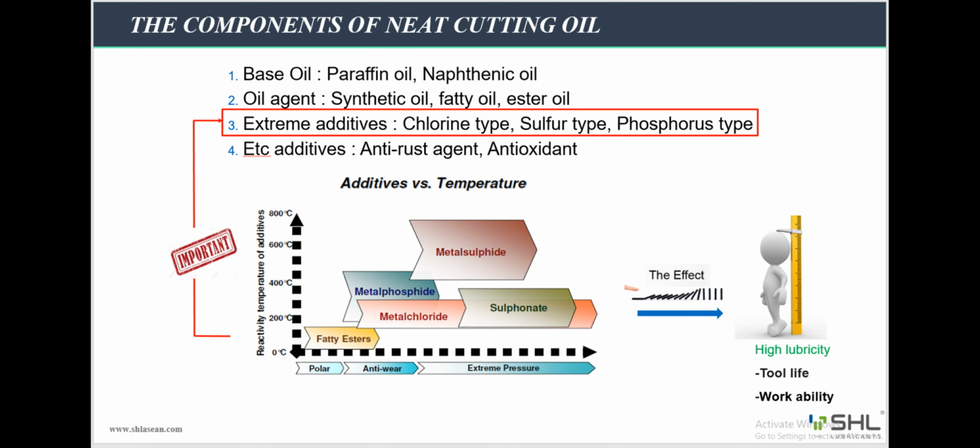On the slide one can see the graph of the dependence of the extreme pressure additives on the temperature ranges used. With sulfur additives, there are two types of sulfur compounds used: active and inactive sulfur. Inactive sulfur is for use at a lower temperature range than active sulfur, and active sulfur is for use at the highest temperatures of the extreme pressure additives.